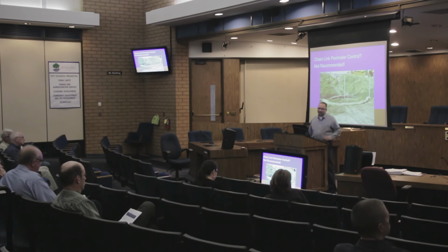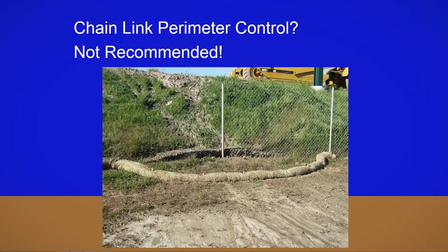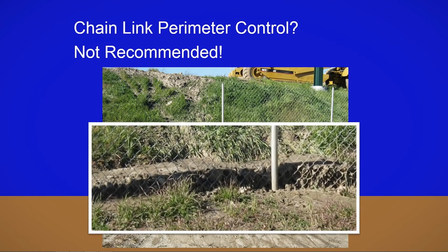All right, to demonstrate that it's not about filtering, I took this picture myself on an inspection I did. Chain link fence can actually be a sediment control. Did you know that? Look at this picture here. This was after one storm. In fact, I'll blow it up. Look at the sediment. If you count links, you can see that there's about 3, if not 4, about 3.5 links. How big is a link? About that big. What is that, about 10 inches of sediment buildup behind that fence?